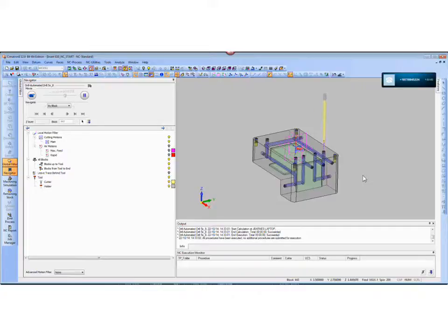So I went back and I changed it so that I only have a length to diameter ratio of a 5, I think a 20, and a 30. But again, it's whatever you want. You decide what drills you want to process with, and you set up the logic, and then you just apply the sequence, and it uses the logic that you build into it.